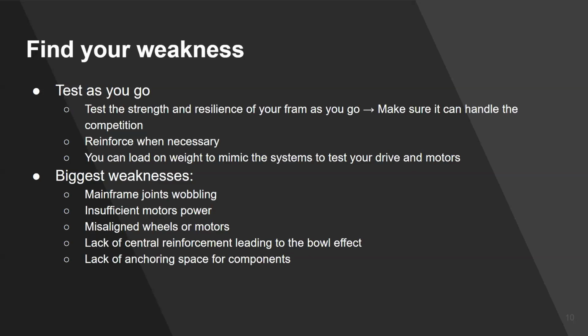Check for misaligned wheels or motors. Sometimes when we design things, we have such a low mechanical tolerance that when you put your motor onto a part of the frame and then you try to attach your wheel, especially if it was something like a tank system, you realize, oh no, they're not quite aligned the way they're supposed to be, or something's off here, it's not driving straight. So test the way that you're driving, and whether everything fits into place when it's put together. And if not, try to find a way, add a tensioner on a tank system. See if there's a way that you can move your motor to a specific side, or see if you have to just altogether change it up. Usually a bracket or two can help to solve that problem.